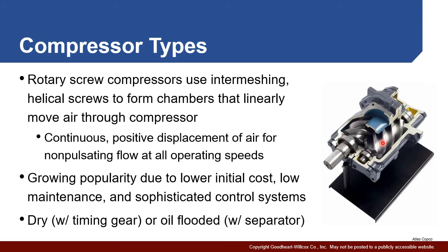Now, originally these were very expensive and we didn't see them in pneumatic systems, but as manufacturing quality has come up and as the availability of these has come up, the price has come down, and we're seeing more and more of these rotary style compressors. They work very well over a long period of time. They have far fewer moving parts than a piston style, and in terms of precise manufacturing equipment, their controls and their output are more accurate.